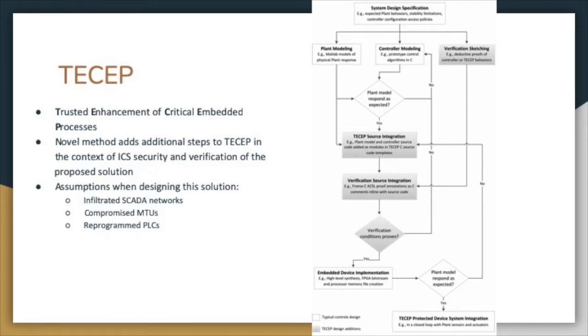This method assumes the worst case scenario where the following have already occurred. The SCADA networks have already been penetrated, and the MTUs have already been compromised. And by the way, MTUs stand for Master Terminal Units, and they monitor, coordinate, optimize, and update the PLCs. And the other assumption is that the PLCs themselves have already been reprogrammed.